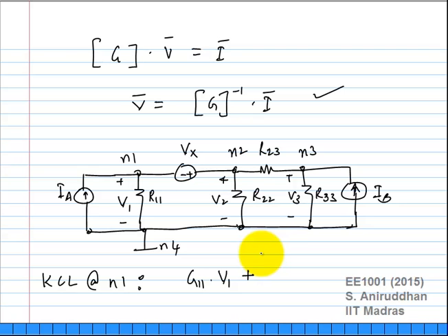From N1 to N2, what do you have? What current is that? Do you know that current? Okay, so you don't know that current, right? In fact, this is a voltage source. That current could be anything, right? That's the definition of an ideal voltage source, that it will maintain a voltage difference irrespective of what current flows through this. So what will we do? So that is an unknown variable. So let me call that Ix. Okay. Plus Ix equals Ia. Okay.